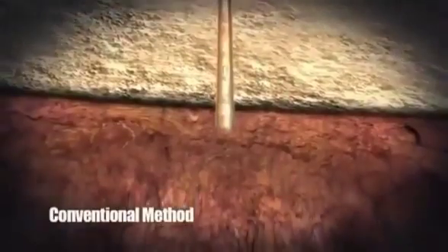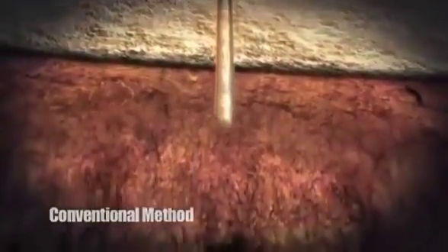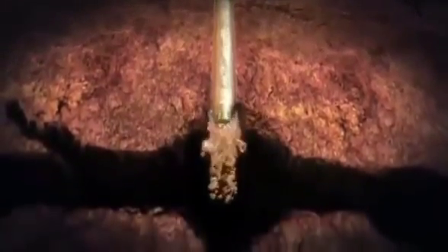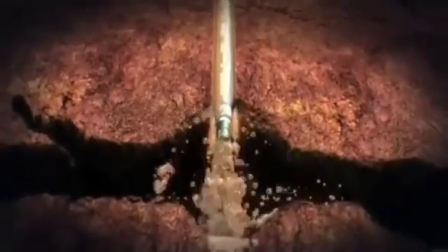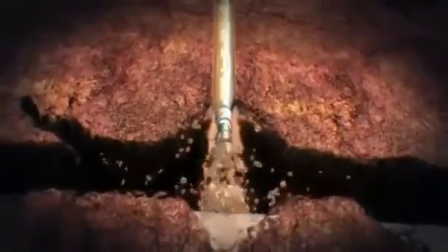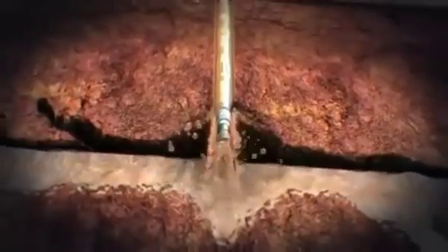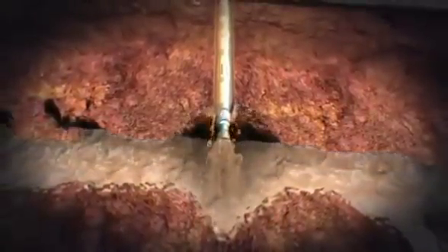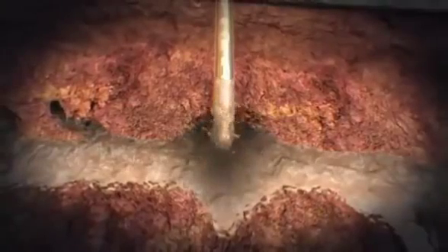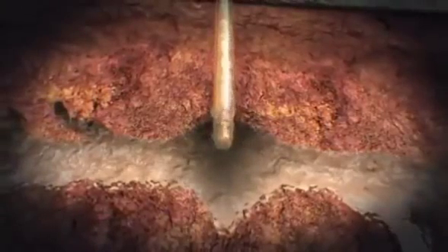Here's the typical scenario encountered with conventional drilling. While drilling ahead, a zone of low pressure is encountered. Pressure exerted by the drilling mud is higher than the formation pressure, and it begins to enter existing fractures and vugs. The driller's first response is to slow the circulation rate and add lost circulation material. If that fails, mud weight is reduced in an effort to match the formation pressure.